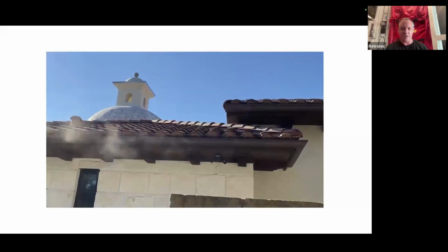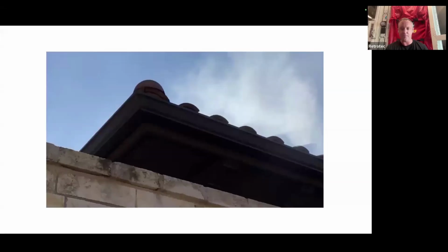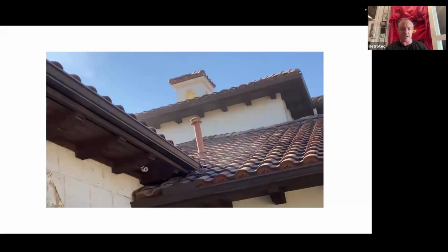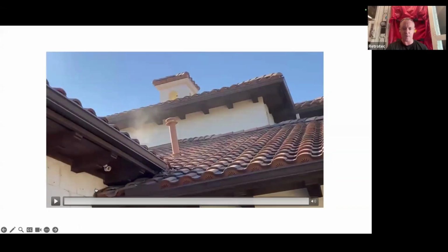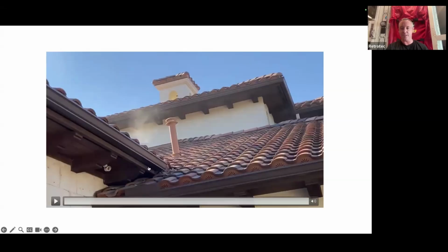So this is what I was talking about before. Those soffits got missed. And that's one of the hardest places to get to if you're going to encapsulate an attic. If you're just getting to it from the outside, you can see there's quite a bit of detail along the bottom of that soffit. So just dropping those isn't really that easy. In a lot of cases, that's what you have to do to really get to it. You've got to drop that soffit board and then give yourself something to spray against right there on the edge. If not, you've got to set yourself something up from the inside. But yeah, here you can see it definitely got missed.